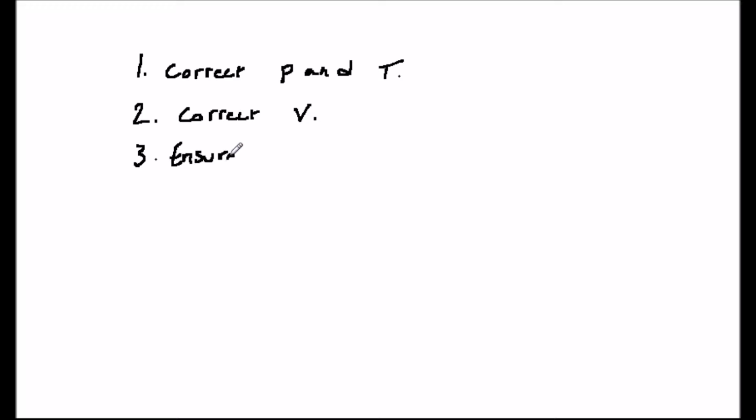So first, let's consider the purpose of the intake in a bit more detail than we have so far. Firstly, it's there to compress the flow and ensure that the correct pressure and temperature are present at the combustor. Secondly, it's there to control the intake velocity so that it arrives at the combustor at the correct speed. Thirdly, it has a purpose to turn the flow into the engine and to ensure that the flow is uniform and parallel internally in the combustor duct.